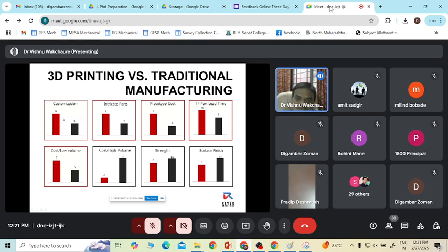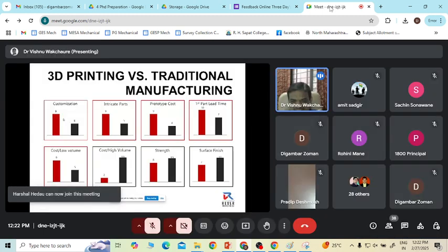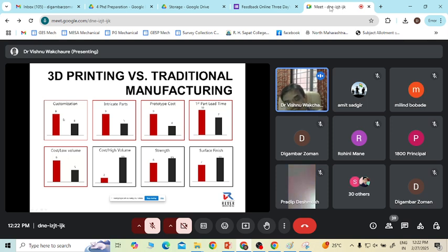But if you choose them properly and have appropriate post processing, meaning once it's printed, you use some residual stress removal techniques like cryogenic treatment and some kind of heat treatments, you can regain the strength. But in that case, to improve the strength you need to select a proper raw material, proper machine, proper machining parameters, and then some kind of post processing that is required for additive manufacturing.